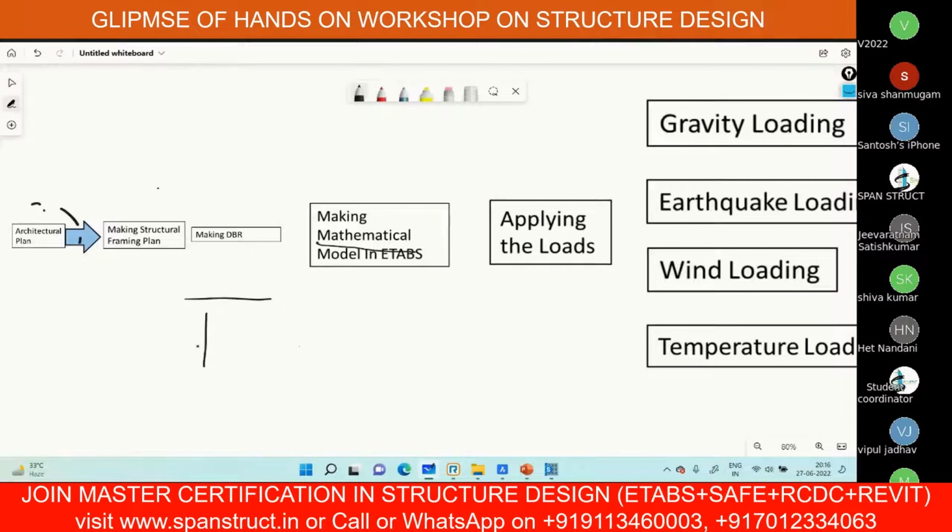Okay. Right, sir. So what are the different steps that can be adopted here to create a mathematical model? How can you create it? The first very common step is you can create it through grid lines. You can create grid lines in ETABS, and you can create the mathematical model through the grid lines. Maybe you have seen grid lines like this, right? Everyone?